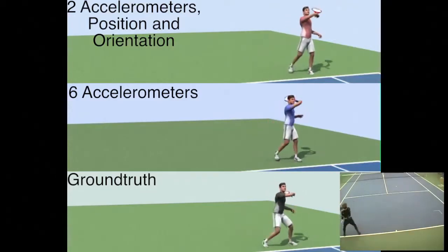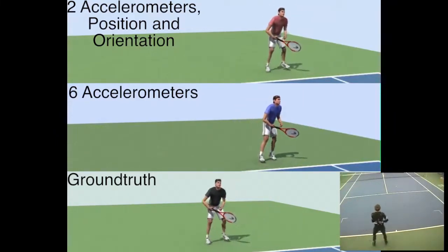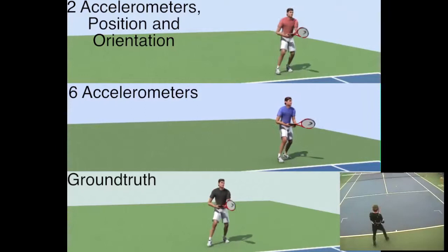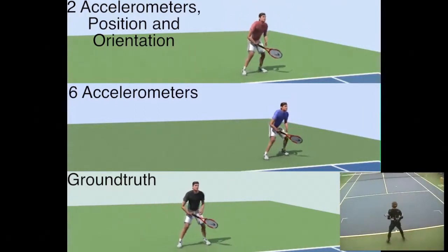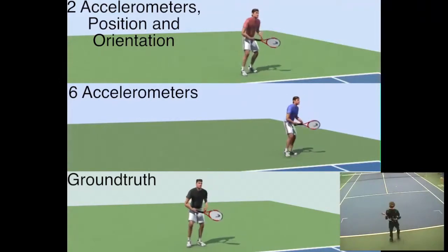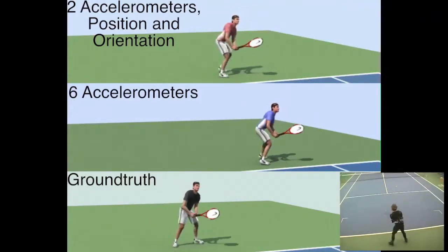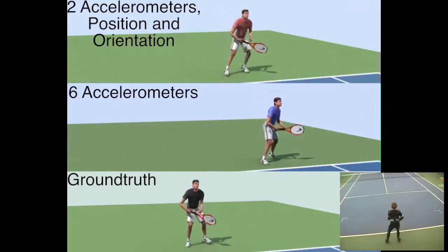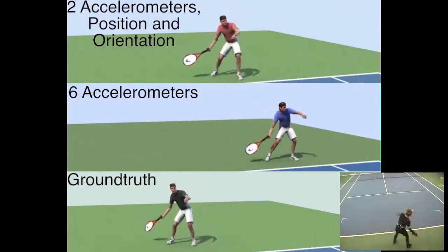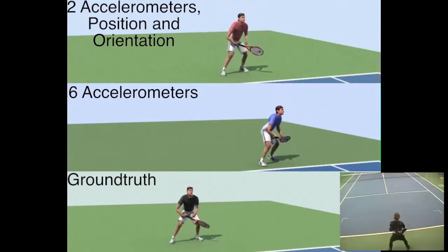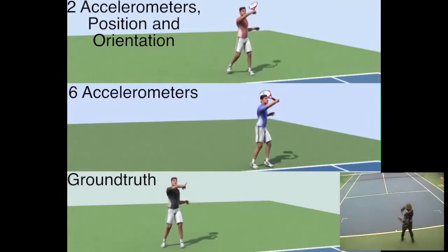In this example, the motion acquired from 6 accelerometers drifts over time. Incorporating weighted global data significantly increases robustness to drift. In addition, the use of global position and orientation data allows the number of accelerometers used to be decreased without affecting performance. The positional data replaces the need for the additional devices, as it significantly reduces the ambiguity of the player's motion between shots.